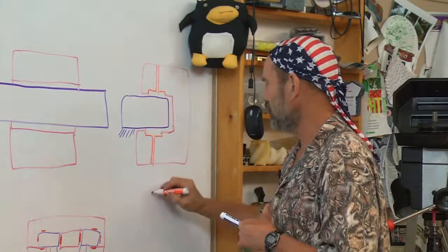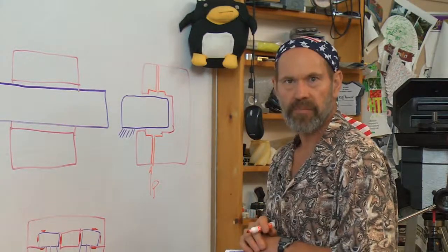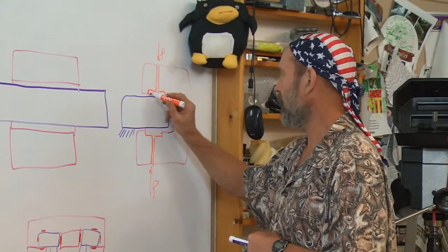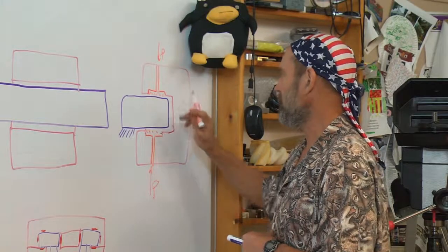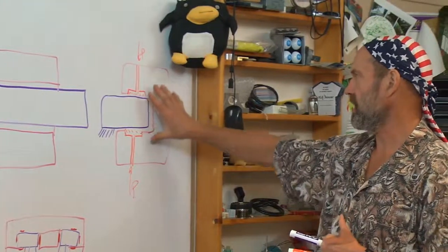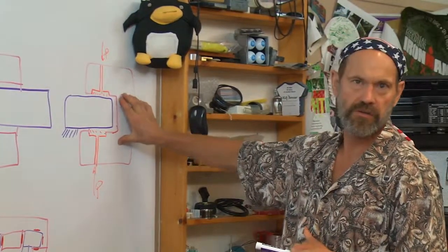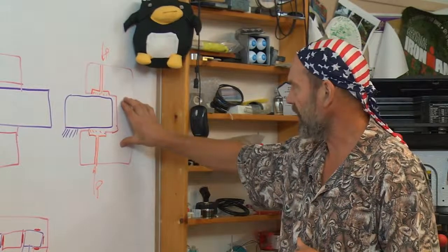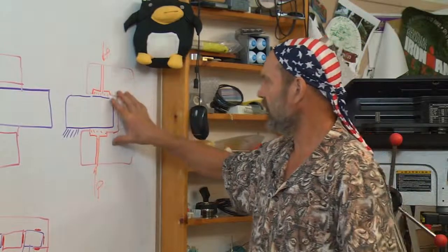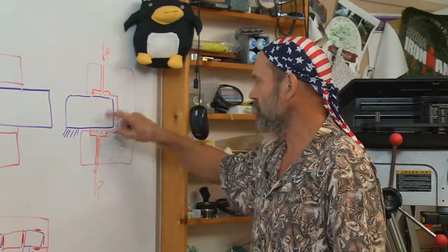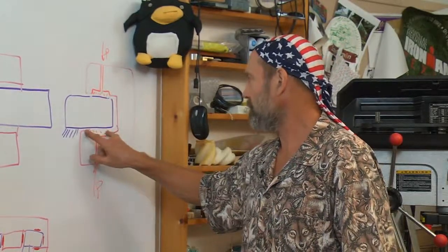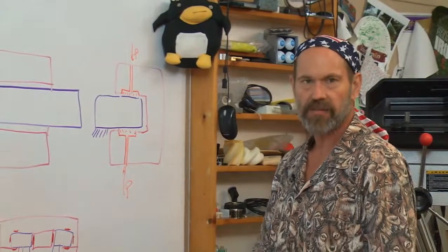And if all I do is provide pressure from a pump, I'll have pressure applied over the area in the pocket to the top and the bottom, and force equals pressure times area. So I have the same force on the top and bottom, and this thing has no stiffness, and then just clunk. It'll go either way. And you say, yeah, but if you push down, this will form a seal in here, and it's got to pick it up. But if it's the same pressure either side, you say, well, it's not going to be the same pressure, because if you push this down, there's no gap here, there's a big gap here, and it's going to have to leak and have a lower pressure.